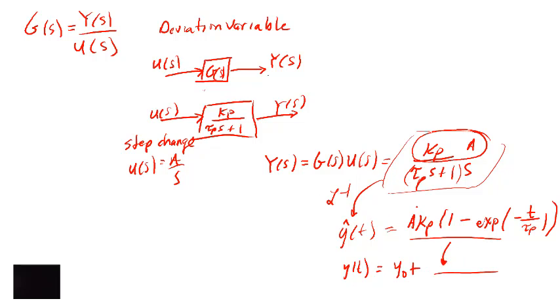And so now we know that we can have various processes where the input affects the output. So we can use the transfer functions to combine processes in a certain way. And so I'll show what that means right there. So if we know that we have an input which is a specified flow rate, and again we have a specified flow rate in the Laplace domain, this would be a variable. And so this variable is going to go through our actuator, and so our actuator will have a transfer function.